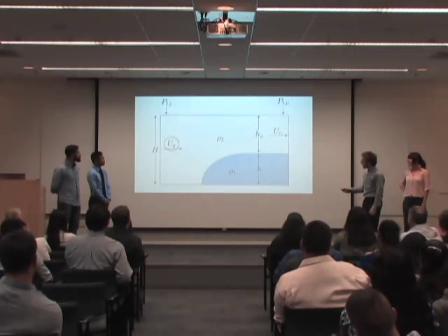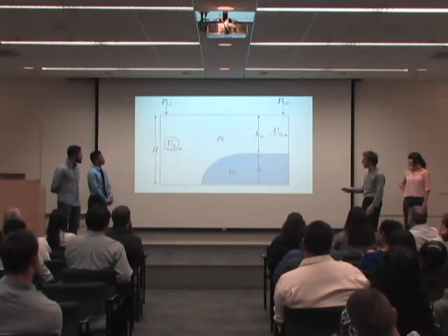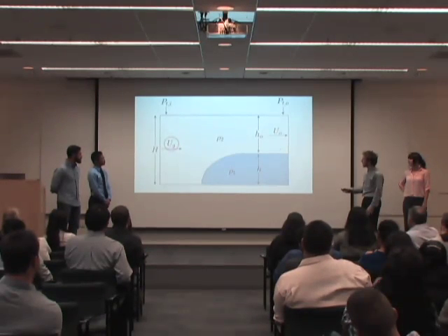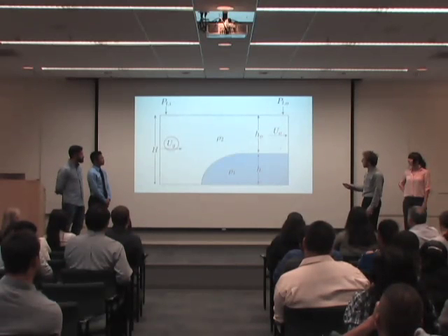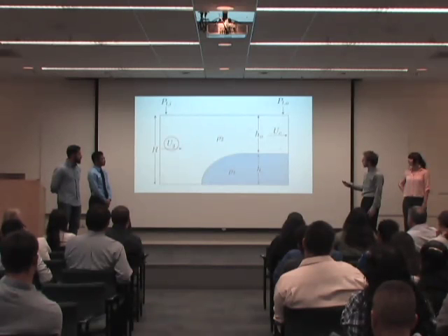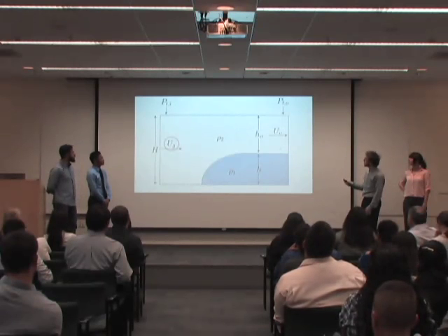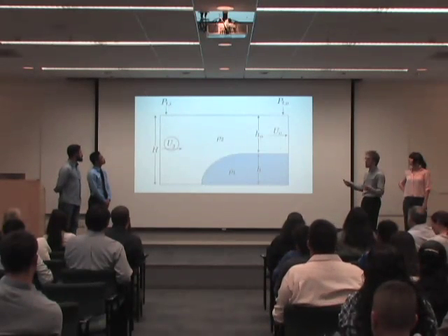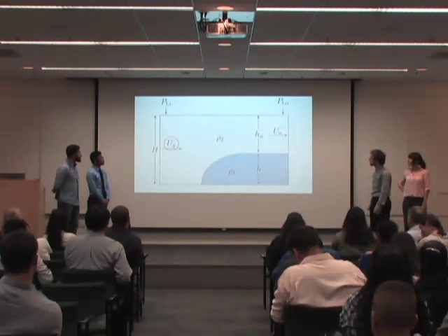Again, our velocity was originally our gravity current. We changed reference frames, so now the inlet velocity is over here. It's the velocity of our gravity current, and the outlet velocity is over here. Additionally, we found we needed to incorporate the height of the exit channel. And while we were solving, we found that we needed to incorporate pressure in our model, which you can see over here.